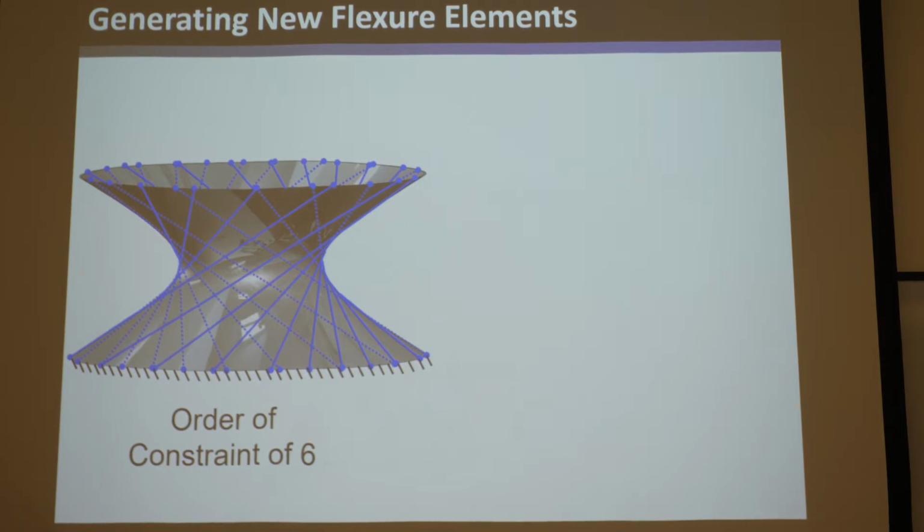therefore its freedom space is nothing. It doesn't move. It's a structure, and if you use this to join 2 rigid bodies together, it would be said to be totally exactly constrained. Even though technically you're like, well, wait, there's tons of redundant blue lines in there, but no, it's a self-contained single element. Elements can never be over-constrained, or it's not useful to consider them such.